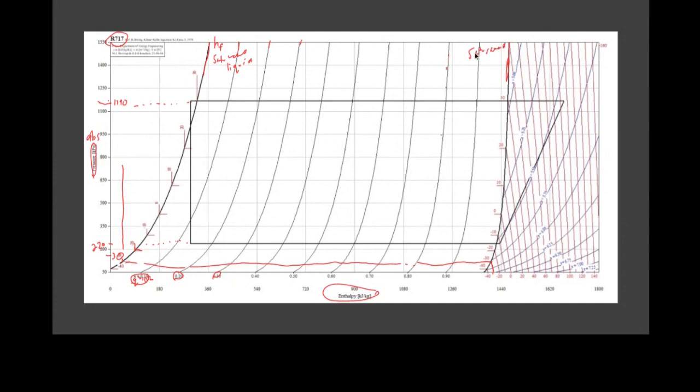If we're looking for that information on our tables, we look at H sub G. And so then we find that, say from this point on the line to that point at a constant pressure, there's a certain amount of energy absorbed in the transformation of something from its saturated liquid state to its saturated gaseous state. And in between the two lines, we've got HFG, right? The latent heat of evaporation. That's in between HF and HG.